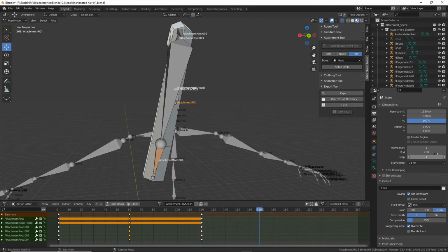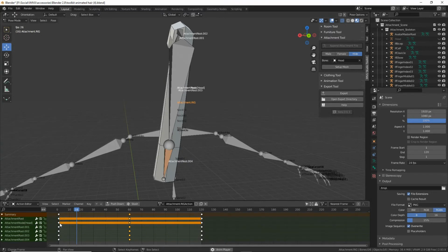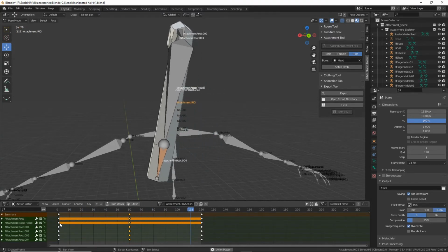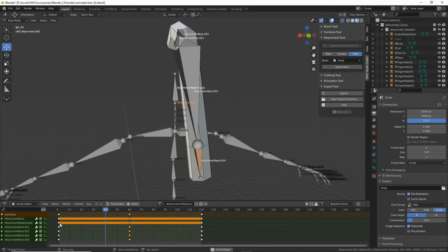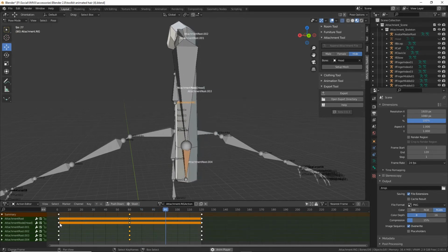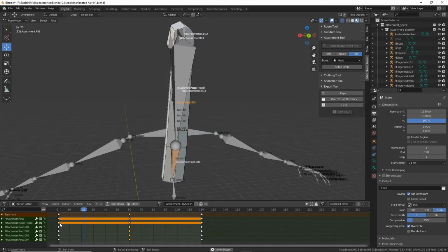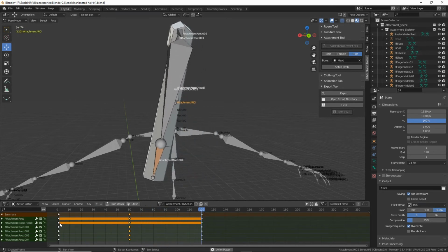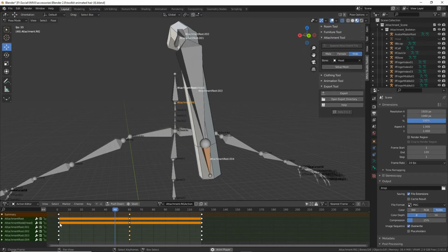All we need to do is click, type 120. That changes the highlighted area from 250 to 120 as we want. So now, if we play the sequence, it'll play just 120 frames and it'll loop. For playback purposes, this is a preview of what it'll do in IMVU.